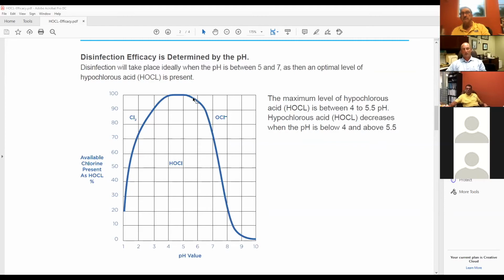And that's why we use vinegar, because vinegar is a very stable, consistent pH buffer. And what it does, unlike muriatic acid, which tends to drop off much faster and then gas much faster, vinegar sits in solution and stays in solution. And so we don't have that same effect that we would with hydrochloric muriatic acid. And that's the key.